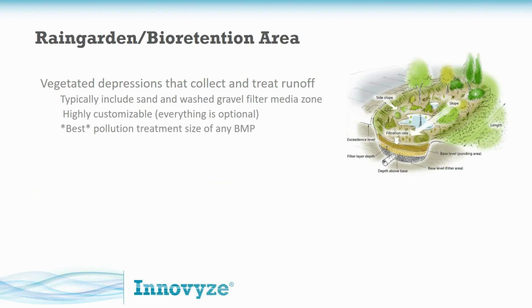Rain gardens, biofiltration, I'm going to call it the best pollution treatment. Like if we were actually worried about removing pretty much name any pollution concentration washing into a facility, there's maybe a couple this isn't the best for, but phosphorus, nitrogen, TSS, this is usually kind of the bang for the buck facility.